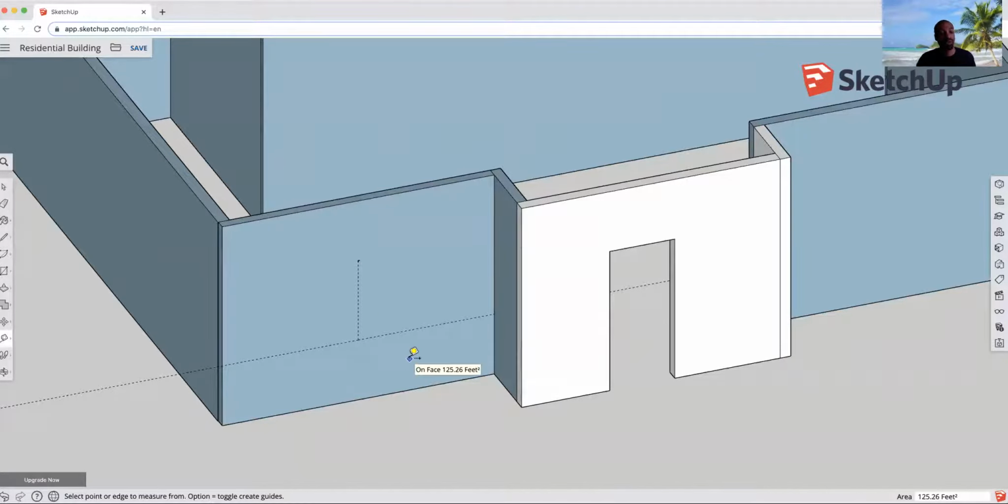Okay, now you can either use it like this, or you could say, okay, what is the distance from the top of the wall coming down until I get to the top of the window? That's going to be 3 feet. So I say 3 feet, enter. It's the same procedure. All right, what that does is it eliminates having this line right here. So I don't need that. All right, so you can either do it one of two ways.